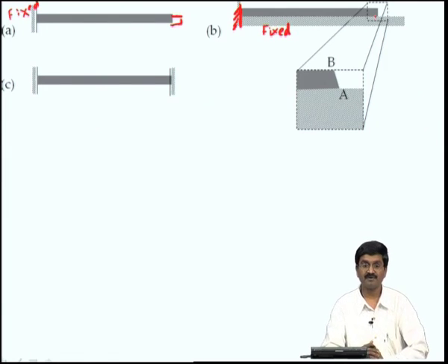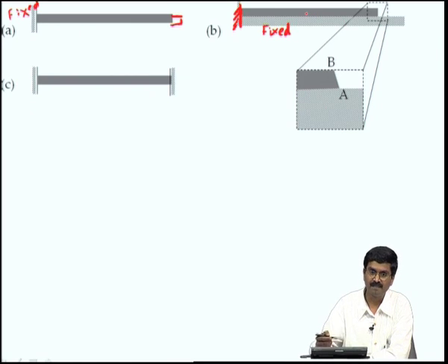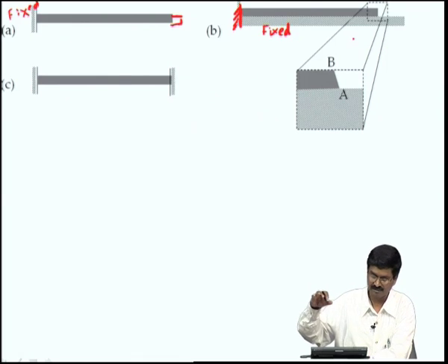Whenever we say that it expands or contracts, it is with regard to heating, but let us say that in the processing of this, we have a substrate, and on top of that we have put another layer at a high temperature and now cooled it back to room temperature. The substrate would have a certain alpha, and the deposited thin layer would have another alpha. If the alphas do not match, one wants to contract more than the other when brought from high temperature to low temperature.